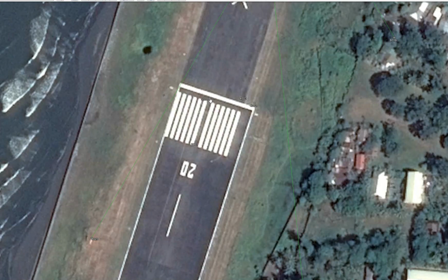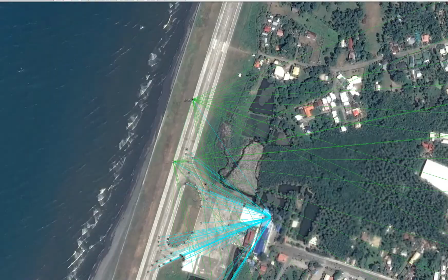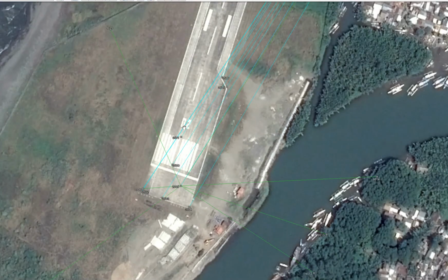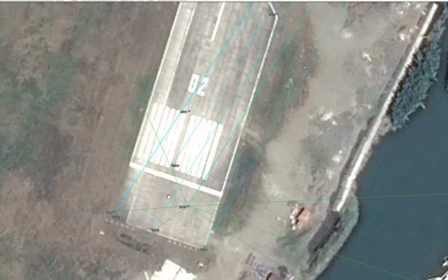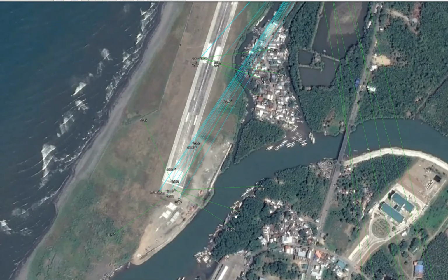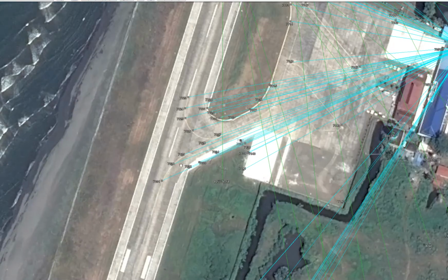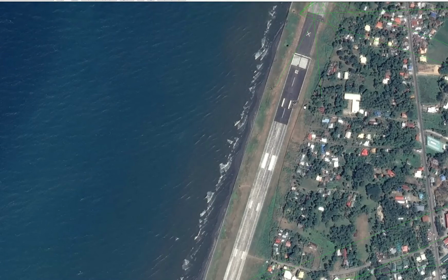But down here, okay, so down here you shot this end of runway, and there aren't GPS vectors into here. So this end of runway is not going to have a good coordinate. Let's see the other end. Okay, so 3500 here, the O2 end, has these GPS vectors. So this is going to be a good position. And then it looks like you shot a few obstructions over in here. So center line points. So it's a good start to the data.